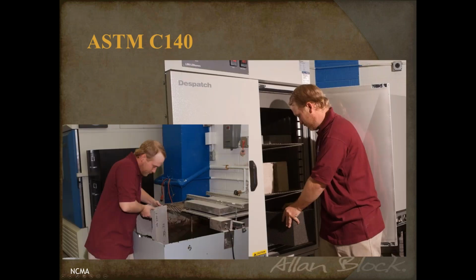And so here's a couple of those photos. This lab tech is putting the standard masonry unit into the immersion tank. They're going to saturate it over 24 hours. This one, he's putting the block into the oven to dry after having got the weight from just lightly toweling it off out of the saturation tank.